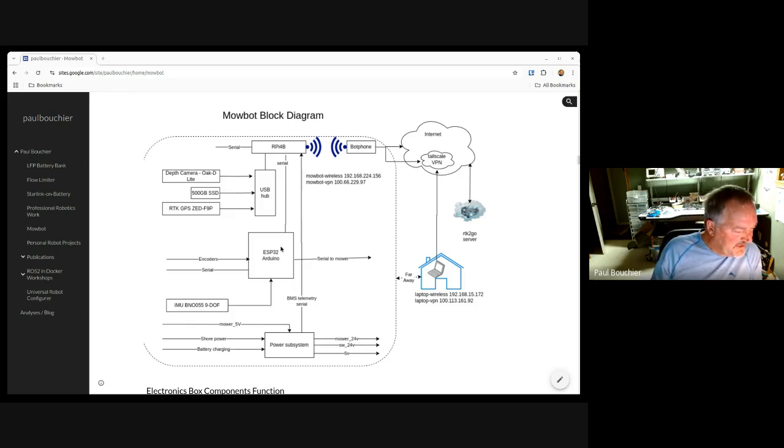And I see this as being kind of similar in as much as you just have to connect to a Bluetooth that you've previously paired. And then I would see it hooking up to the ESP32 Arduino. So we've got the Raspberry Pi 4 running the autonomy, path planning, obstacle avoidance and high-level software. You've got an ESP32 Arduino accepting encoders and sending motor commands, so doing low-level machine control stuff.